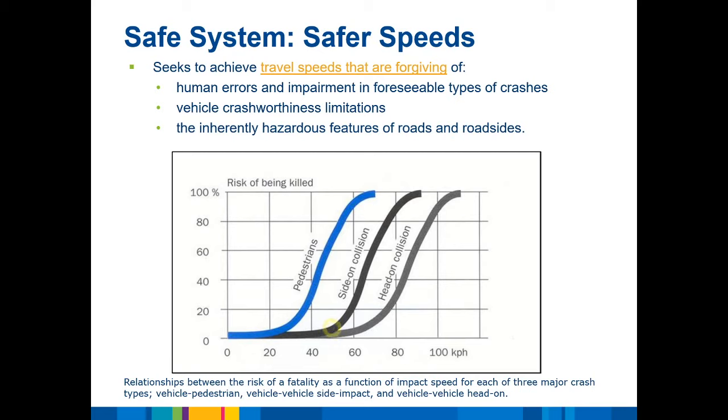And so again, we're saying we need to do things. We obviously are still going to have high-speed roads that intersect at right angles, but we need to do things to minimize this chance of a side-on collision. How can we do that? What can we do to change the shape of the intersection so that at least the angle is not 90 degrees, or at least the speeds involved in the angle are not going to have a vector sum of 50 kilometers an hour?